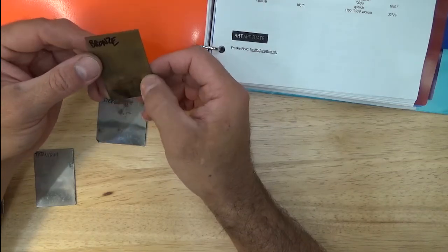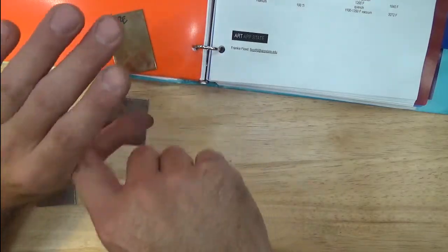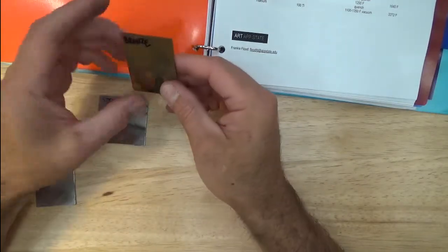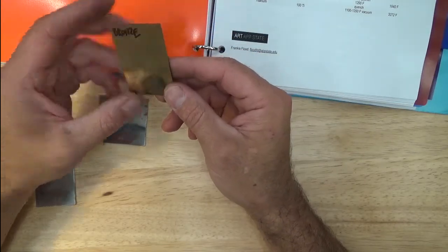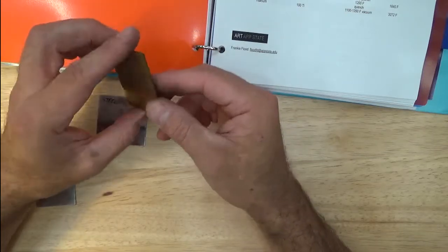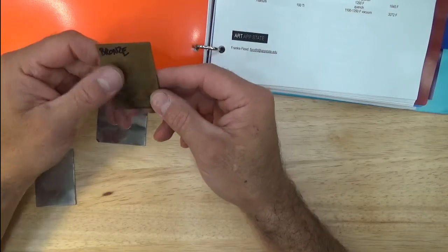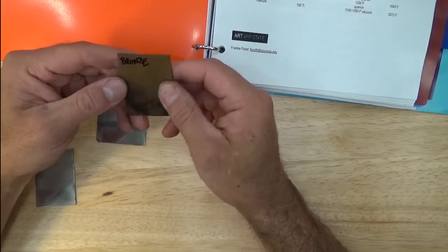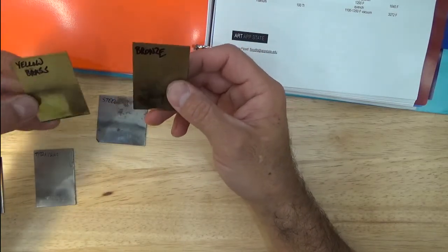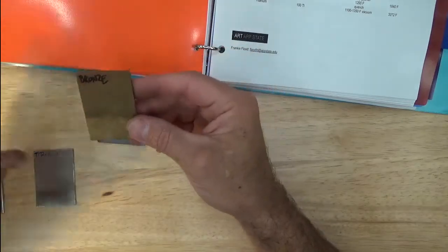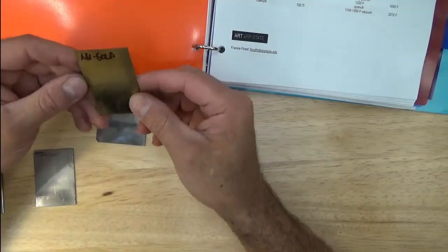And you'll see bronze used a lot in bushings and bearings, where you've got maybe a steel surface rubbing against that bushing on the inside, and so it's great for moving parts as a bearing surface. You also see it used a lot near water as well, right? Because it can resist corrosion. It will build up over time a slight patina, a darkish patina more quickly than brass, but great material to work with. It can also be silver soldered, by the way.